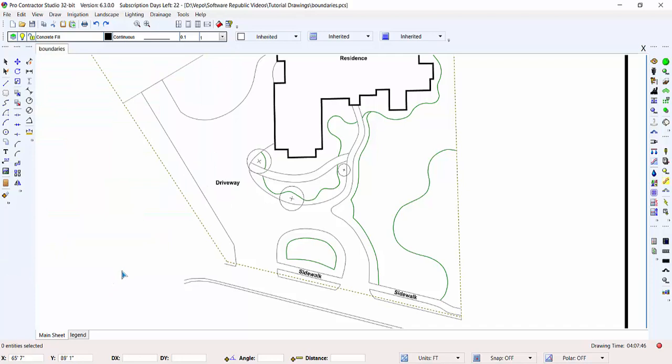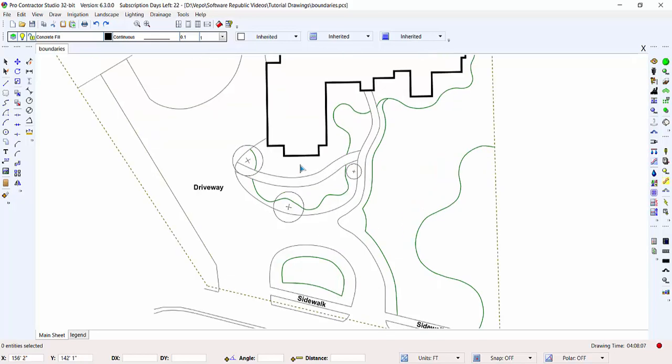You can create a boundary line by setting a point within a closed area or by selecting the lines, curves, circles, or arcs that make up the area. It's important that the entities intersect each other and create a completely enclosed area. If the entities do not create a closed area, the command will not work. You must make sure the entities intersect each other.